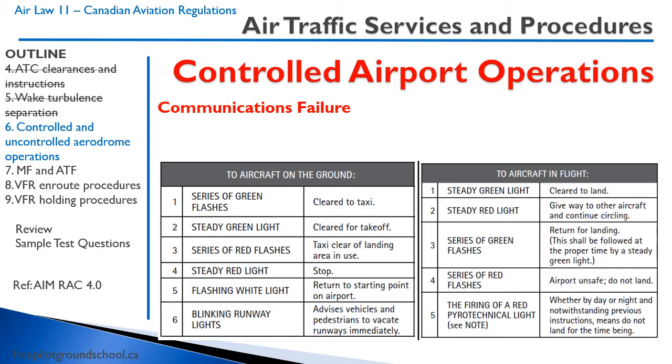They're usually quite understanding. Having said that, can you guess what the biggest reason for communications failure is? Well, unfortunately, it's pilots screwing something up on the radio, pushing the wrong button, talking on the wrong radio, doing something like that. However, if you do have a communications failure, there is a standard squawk code. Remember your transponder that we just talked about? That code is 7600, 7600.